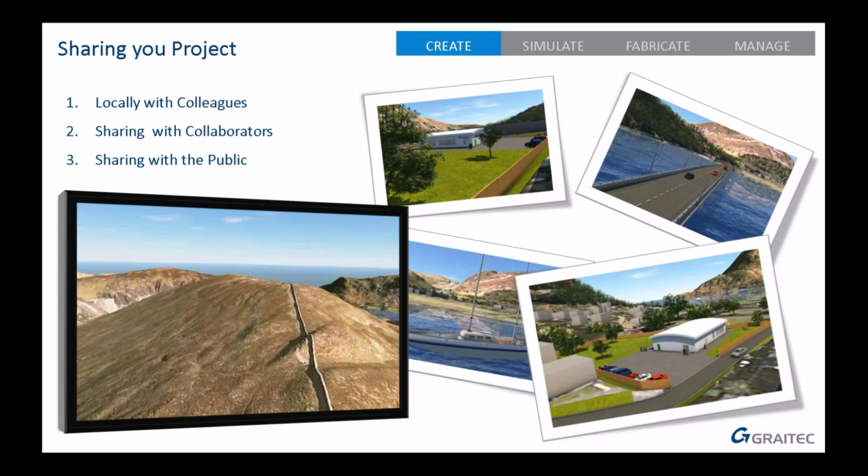Here's your problem. The Revit algorithm smooths it. If you were doing a design surface with jaggedy edges, Revit won't read that. Apparently, I've had mixed results on this. I think they've improved it recently. If you publish the surface, it is a more accurate representation, which is good. But the next problem is, if you remember, that surface probably has 1 million points in it. And if you put 1 million points into your Revit, bad things might happen. So there's lots to consider. The answer is not really, but yes, you can go from Civil 3D to Revit.